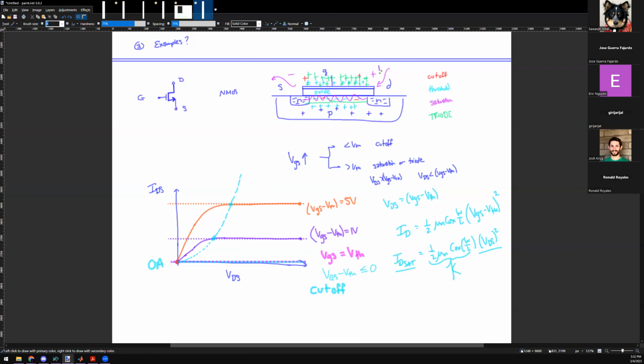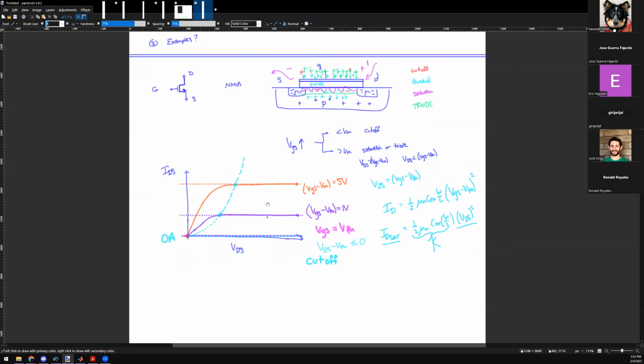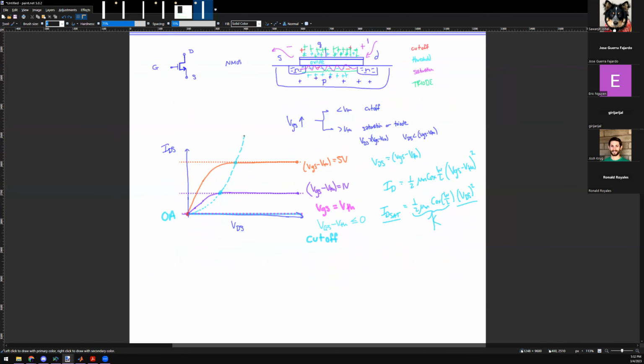And do you see how from this physical circuit, we could generate all of it? Conceptually, we could walk through the trends of what it means to be saturated, what it means to be in triode, and so on and so forth. Yes? All right, beautiful, good job. So basically this area I will call triode. Anything left of this is triode, and everything after this, I am saturated.